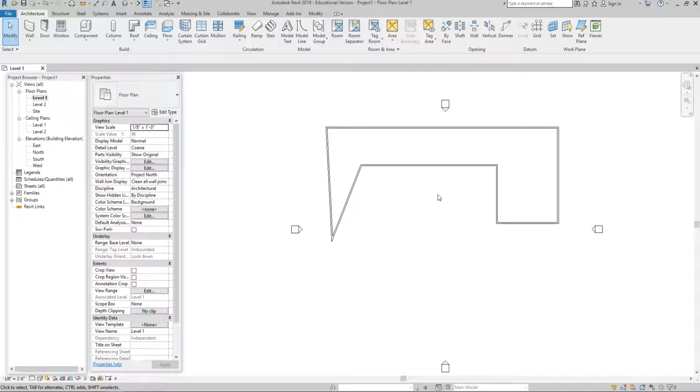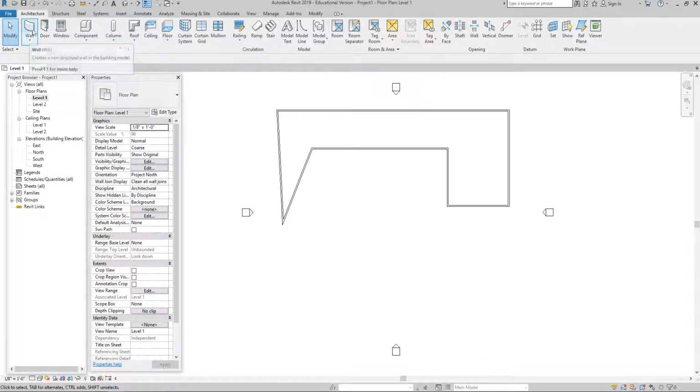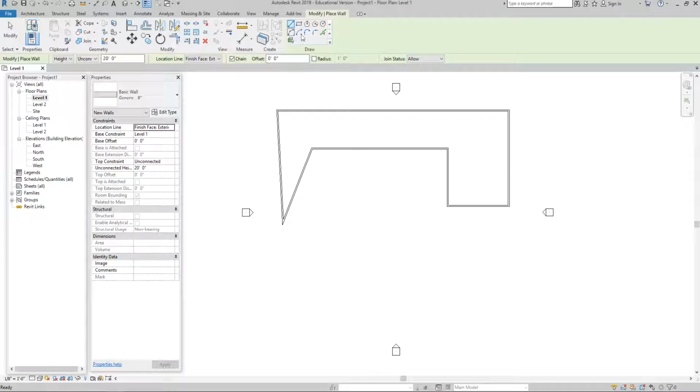All right, so let's talk about the pick command. I use the pick command all the time for so many things. And what I like about the pick command, I'm going to initiate the wall command here first. What I like about this pick is that it very easily allows me to create dimensionality, right? Where I think that is maybe a weakness in Revit, like I said. A lot of times I'll create things and I'll get them as close as possible, but I always have to go in and revise it, right? Because I'm not sure if the dimension is correct. So I'm pulling a lot of dimensions, I'm double checking things, all things you have to do in a computer-aided drafting program anyway.